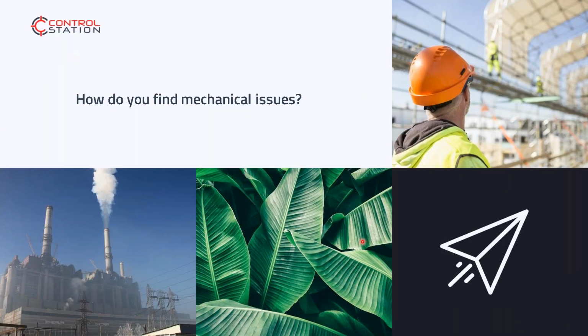Okay, thanks, Michelle. Interesting results there. We're going to actually talk through those 3 components, stiction, deadband, and hysteresis, just to give you a dictionary definition of them, but also then to understand their potential causes, because that's part of my why am I here question. Why is this valve not doing what I wanted it to do?